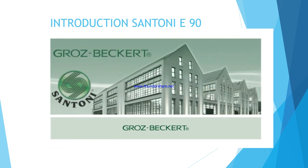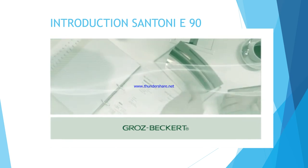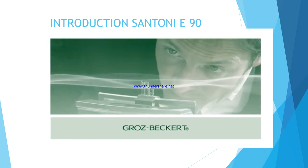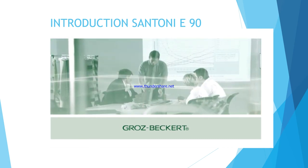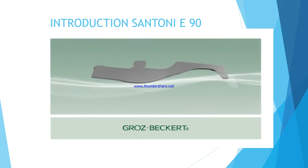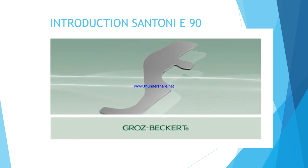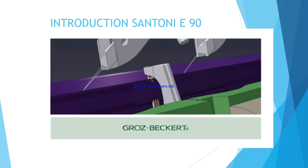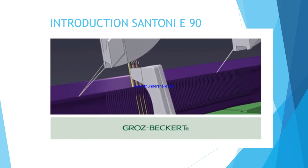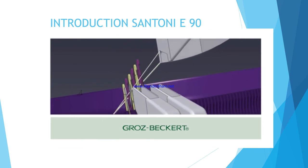The cooperation between Santoni and the Technology and Development Center, TEZ, has allowed Groz-Beckert to develop and build the textile parts, needles, holding down jacks, cylinder, for the loop formation. The holding down jack is made with high precision because in its working phase it has to contain 2 needles. The needle guide function is carried out by the lower part of the holding down jack, which causes, in case of possible swings, the displacement of both elements with resulting lack of shocks.